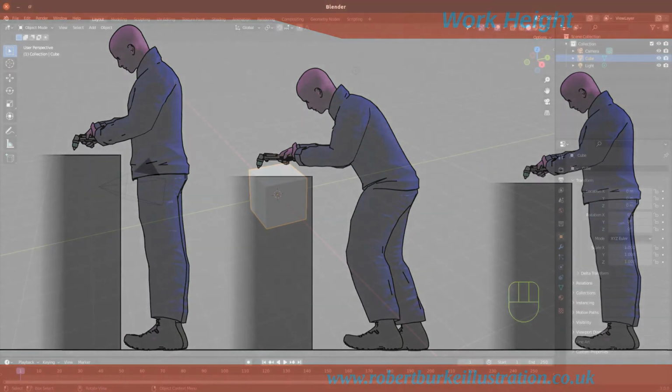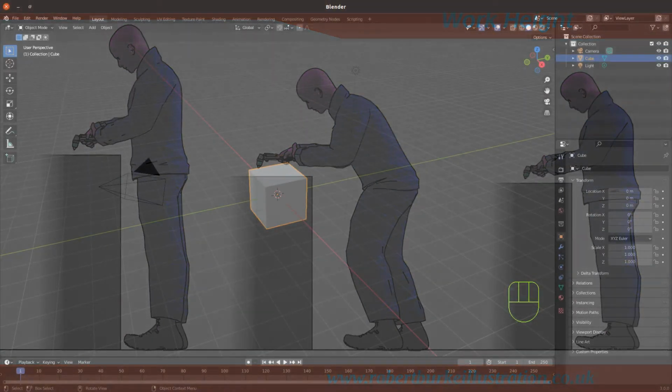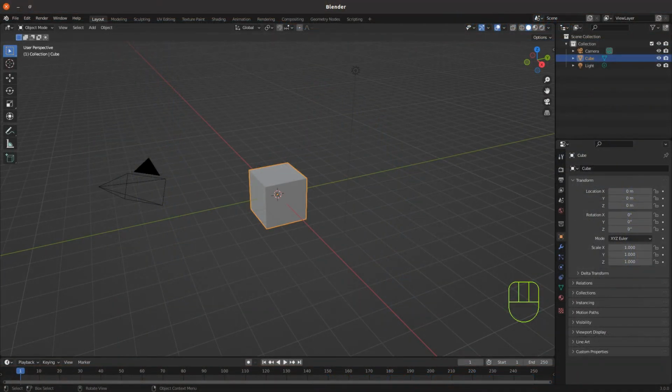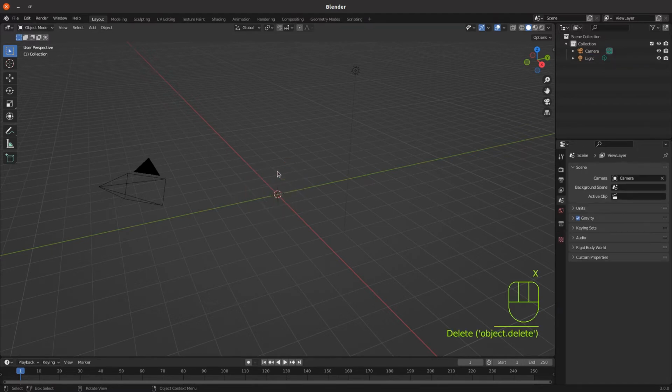When you're happy that you've determined what height you want the table to be comfortable working on, we can open Blender and first of all put a representation of where the tabletop will be within the Blender 3D environment. So first of all, the default cube isn't that useful for it. It can be used, but I'm going to delete the default cube, so press X for delete and accept delete from the pop-up menu to get rid of it.